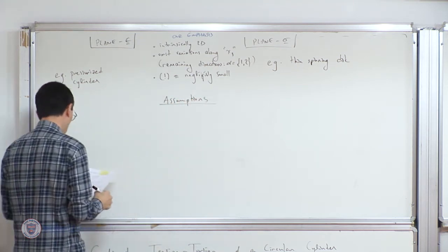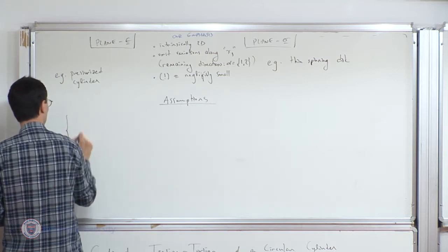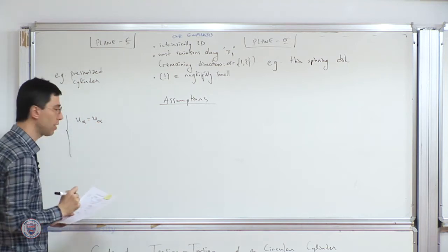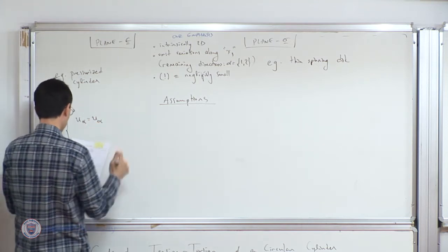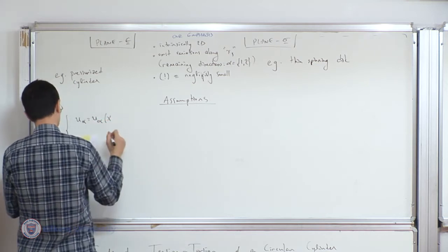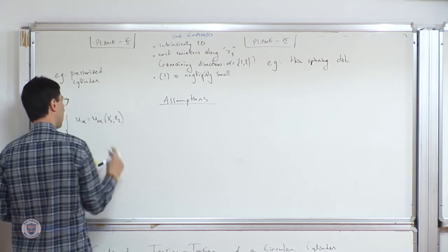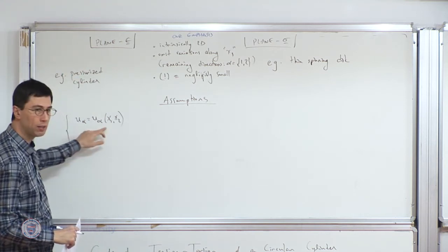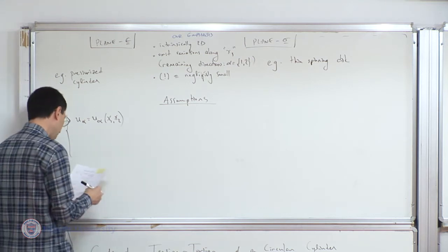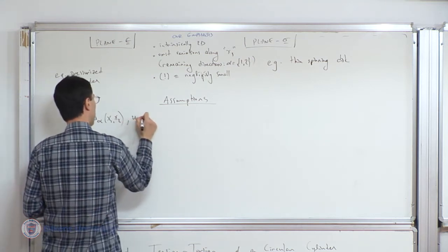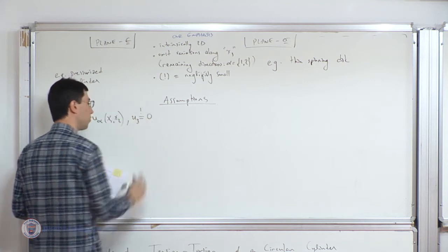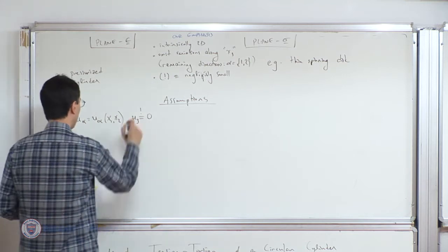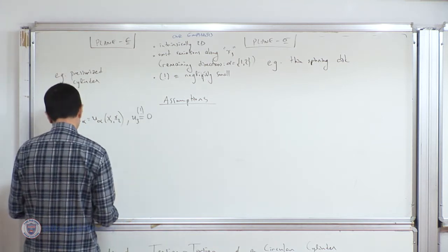OK, so let's first recall what the assumptions are in these two settings. On the left-hand side, we have the displacement components. And because it is a plane strain problem, I will, in that setting, only be concerned with displacements in the 1 and 2 directions, u alpha. And u3 is equal to 0, perfectly or nearly. So it's negligibly small or perfectly 0.